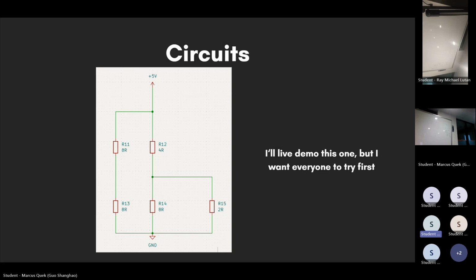Parallel resistance does not simply add up. The reciprocal adds up. So if you have, for example, 8 resistance and 5 resistance, your total should be something like 4 resistance. If it's not, then you're doing something wrong. You add up the reciprocal of each individual branch. So let's say one branch is 8, one branch is 5. I get 1 over 8 plus 1 over 5. That equals 1 over something, and that something is my total resistance of the branches.